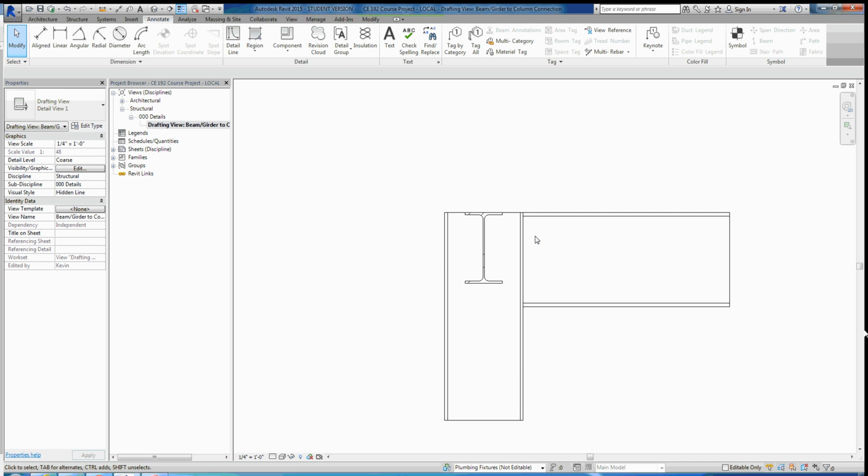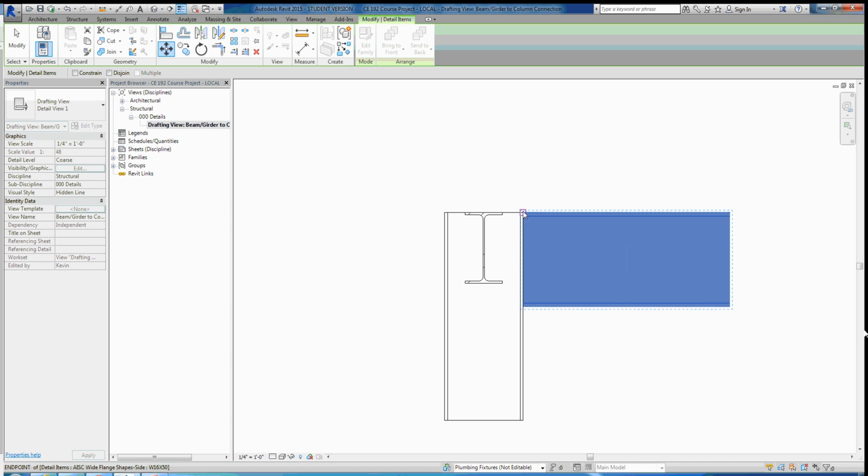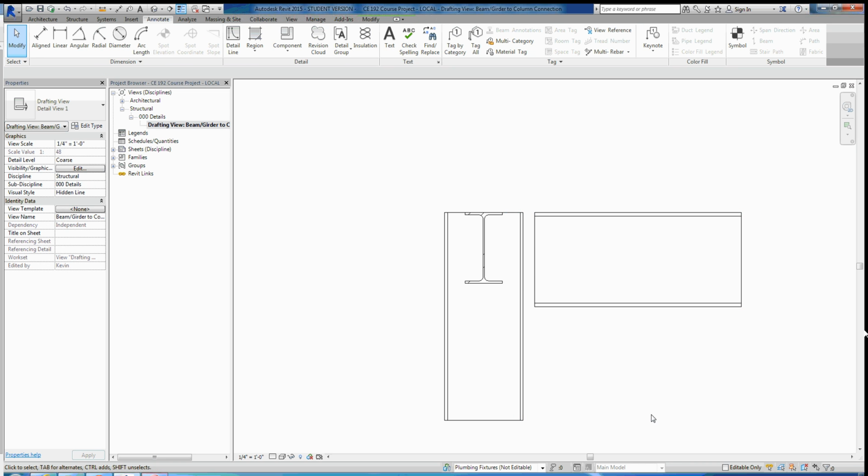And we can see if you tried to get an extension here to make that 2-inch gap right off the bat, it's not going to really work out very well for you. Revit is a little finicky with using extensions and certain things like that, so sometimes you'll just have to add an intermediate step. So what I did is I just drew it right on this corner. Now I can click it, hit Move, and move it over 2 inches pretty easily like that. Sometimes it takes a little bit of creativity to make sure you can do what you want in Revit, because its tools aren't quite as powerful as AutoCAD's.